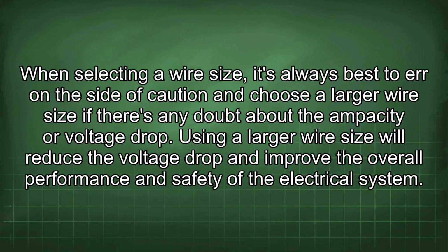When selecting a wire size, it's always best to err on the side of caution and choose a larger wire size if there's any doubt about the ampacity or voltage drop. Using a larger wire size will reduce the voltage drop and improve the overall performance and safety of the electrical